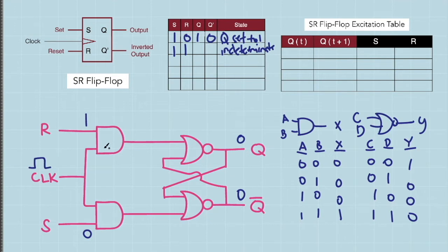So essentially, these inputs here are both logic 1. So for this first AND gate, its output would be logic 1 and this is 0. And the output of this NOR gate will be 0. Next, for this AND gate, its inputs are 1 and 0, hence its output will be 0.